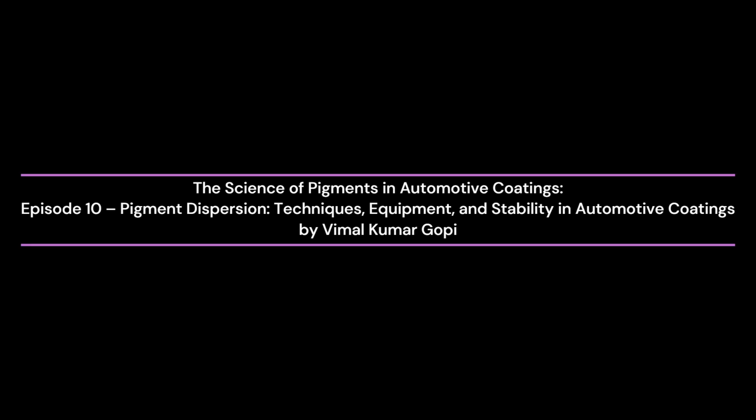Effect pigments and pearlescent pigments require special attention. Because their optical performance depends on particle orientation and integrity, excessive milling can reduce flake size, create fines, and degrade metallic or pearlescent effects. Low shear dispersion techniques combined with optimized surfactants are often used to maintain flake morphology while achieving adequate wetting and distribution.